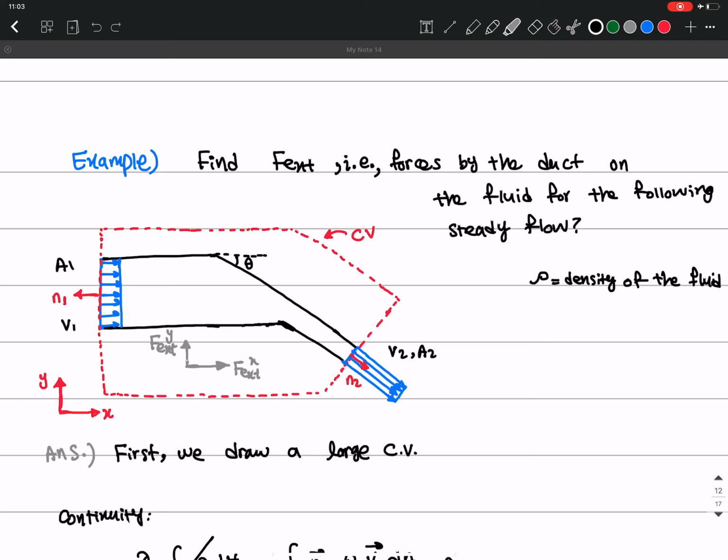And we found an equation which we simplified by changing the variables. But we still need more equations because we have three unknowns: F viscosity, delta, and uy. So we also used the Newtonian fluid assumption for this problem. And so we got this equation, but we still need one more equation because we have three unknowns, to close this set of equations in order to be able to find F viscosity.